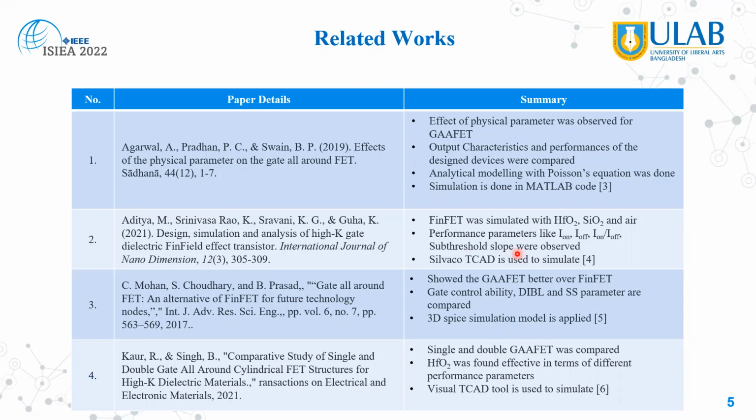In the third paper, they showed GAAFET is better than FinFET on the basis of gate controllability, DIBL, and subthreshold swing. In the last paper, you can see single and double gate GAAFET are compared. They used the Silvaco TCAD tool to simulate the device, and they found hafnium oxide effective.